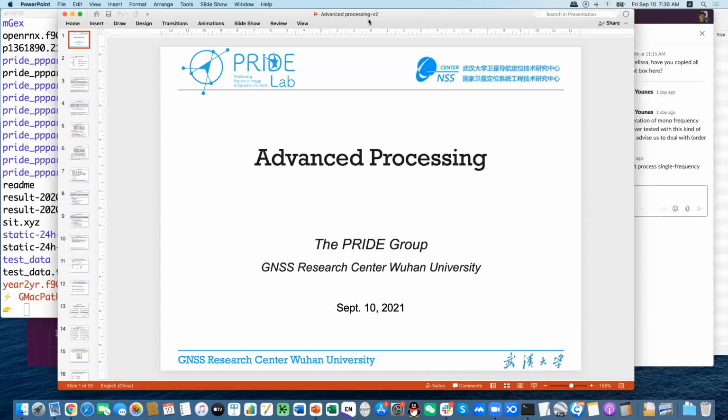You can use only 1 hour of data to get the seismic waveforms generated by ground shaking. And 24 hours of kinematic processing can be good for early post-seismic data processing. You can see after the earthquake, especially after some large one, there are very rapid post-seismic signals. I have students working on this for the Chilean earthquake.